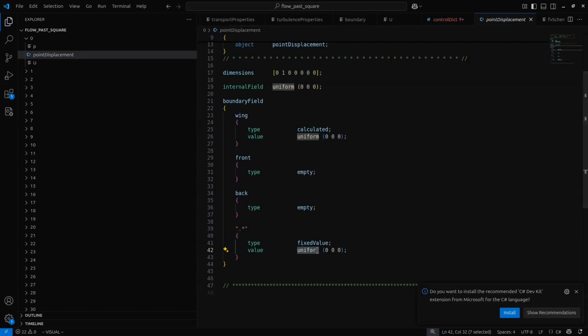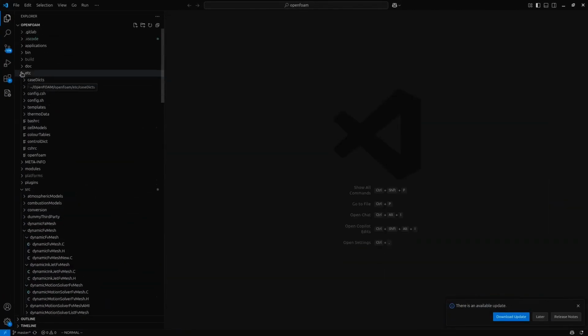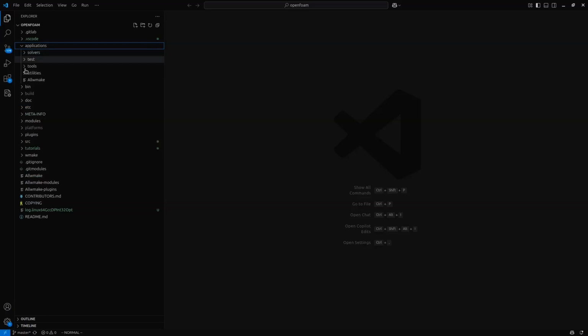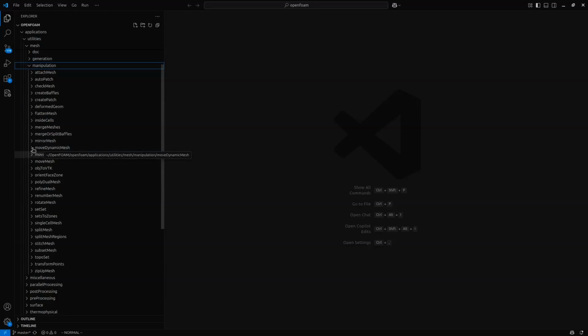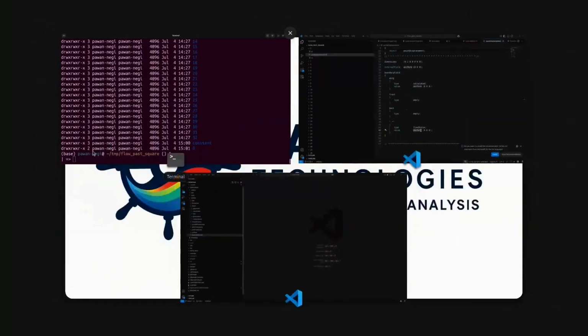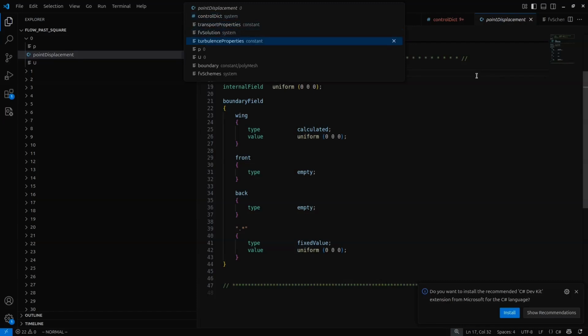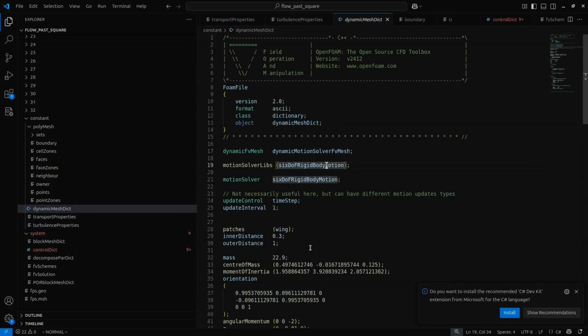Let's go to the source code of OpenFOAM. Let me open that. First of all, this is our OpenFOAM source code, and here we can see all the solvers, and in the utilities, in mesh, in manipulation, we have methods to move the mesh, which is moveDynamicMesh. We have to find out that when we are using one of them, how do we know what the parameters involved are. First of all, this is the bare minimum that you should know, what kind of file you have to write. Unless there is an example, it is very hard to find out what kind of file you have to write. This much is the bare minimum. You should get this from one of the tutorials. Then you have to go to